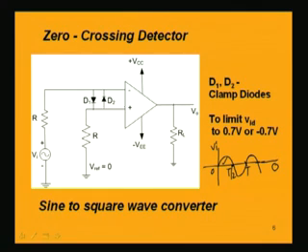So, if in the positive half cycle we consider the voltages such that this is V1 and this is V2, the difference voltage is V1 minus V2, but we have to take care of the connection of the clamp diodes, because when Vi is positive, as it is greater than 0, diode D1 will be conducting. So, diode D1 conducts and the drop across this diode will be 0.7. So, what will the output voltage be? Output voltage is V1 minus V2 into A, because VID, which is V1 minus V2, is now minus 0.7, because this drop is 0.7 across this diode.